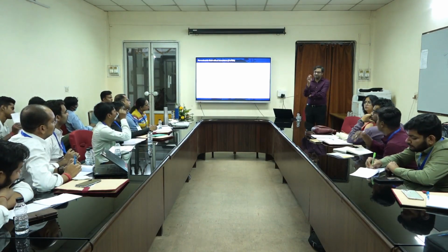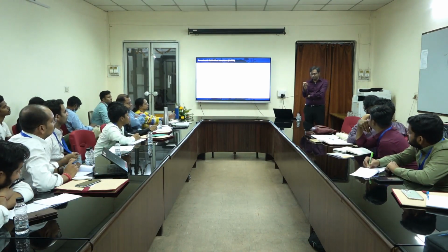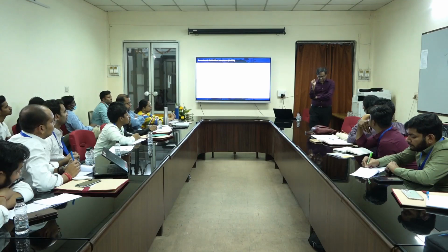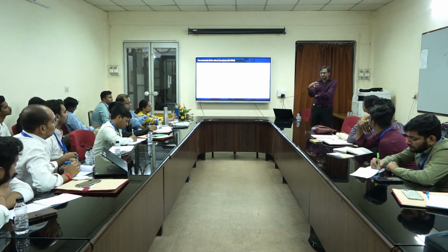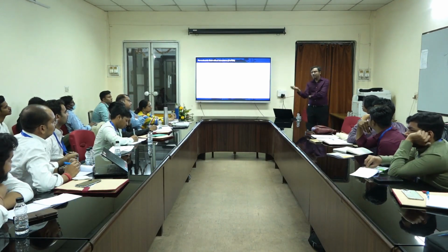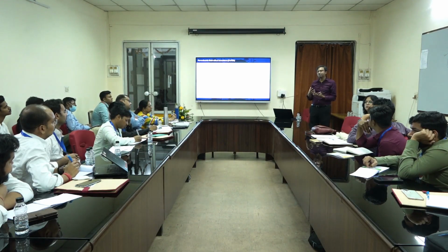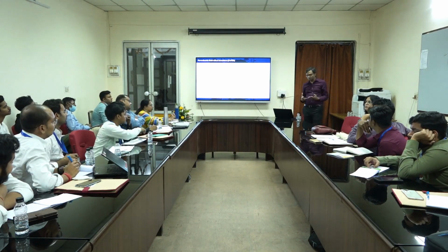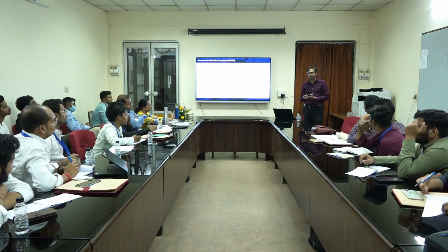Now, these memristor devices have their own advantages, right? Because this is 2-terminal, they could be even smaller because there is no need for a 3rd terminal. But it also has certain disadvantages because they can only store information and cannot do computation. Transistors are good for both computation as well as storage. So when you are thinking about a really multifunctional device, a 3-terminal device gives you a lot more flexibility compared to a 2-terminal device. But having said that, you can use MoS2 as a memristor.